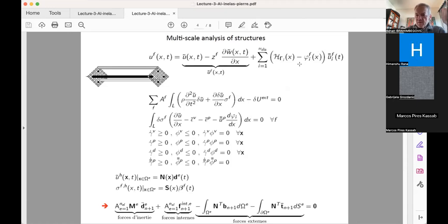And then when you have a crack, you have a Heaviside function minus a function which is describing how the crack dies off from this point where it is introduced. Typically, this is taken in terms of the shape functions of particular elements. We'll talk about that in a moment, well, next lecture rather. And then times the jump, the crack opening or particular stuff.